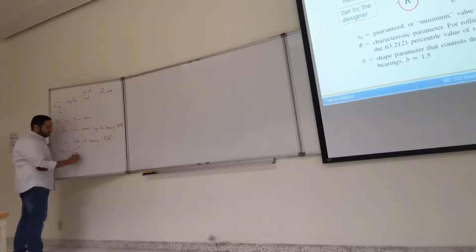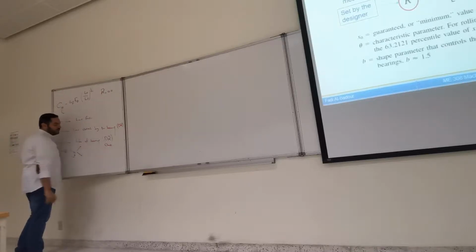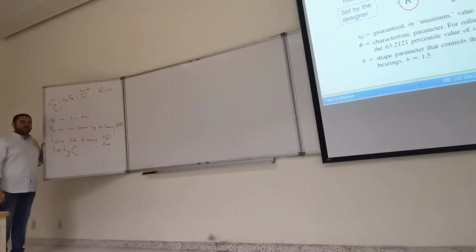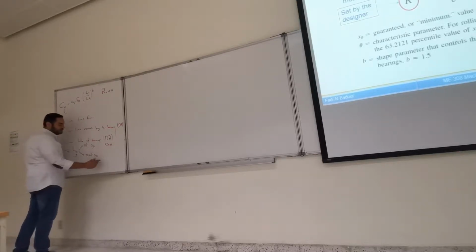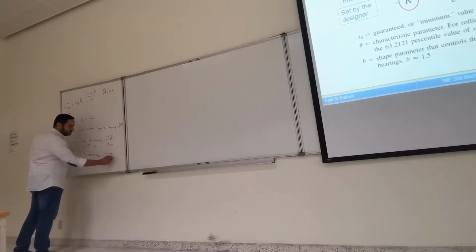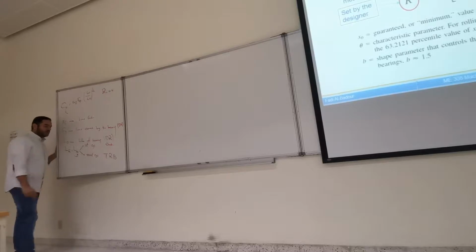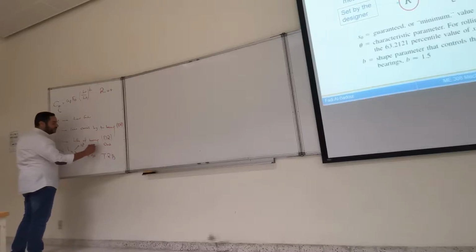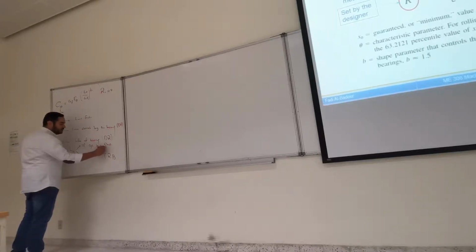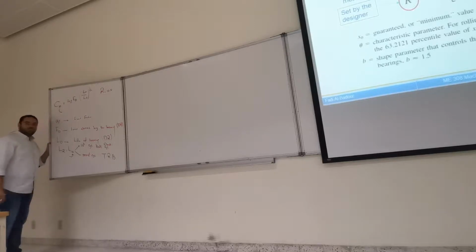It is a constant parameter. The value is determined by the bearing manufacturer, based on the tests they do. So we have two groups of life: 10 million cycles and 90 million cycles. The group of bearings that use 90 million cycles is the tapered roller bearings, those types of bearings that are good at carrying both thrust and radial loads. The remaining ones, ball and cylindrical, go with the other value.